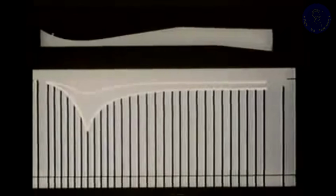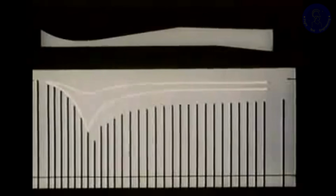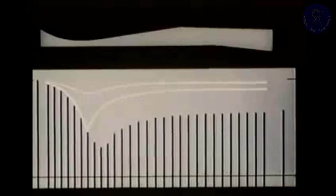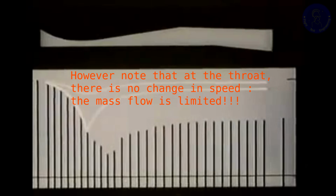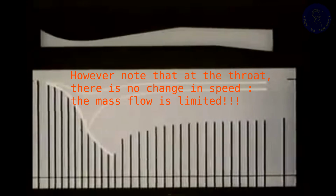As we continue to open the valve, the symmetry disappears. Notice that the pressure and velocity upstream of the throat are not changing. Just downstream of the throat, the falling pressure means that the air is accelerating in the diverging part of the channel.